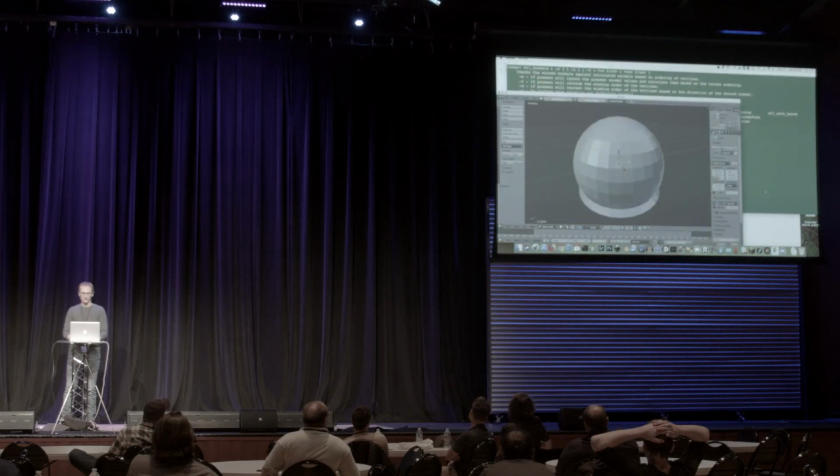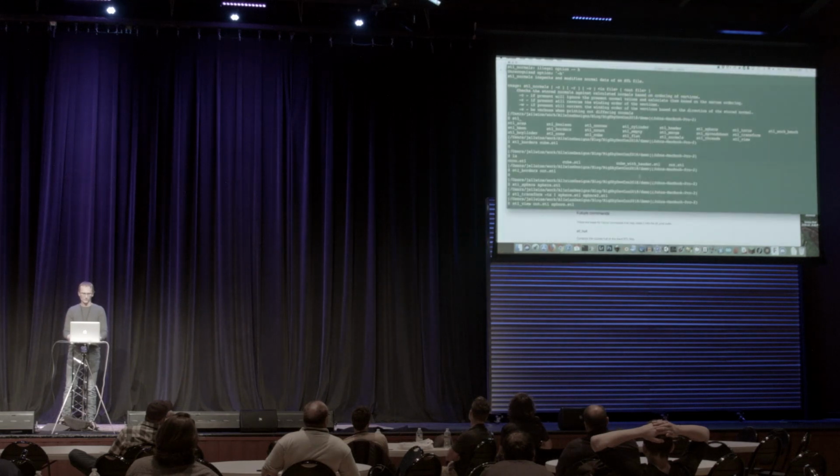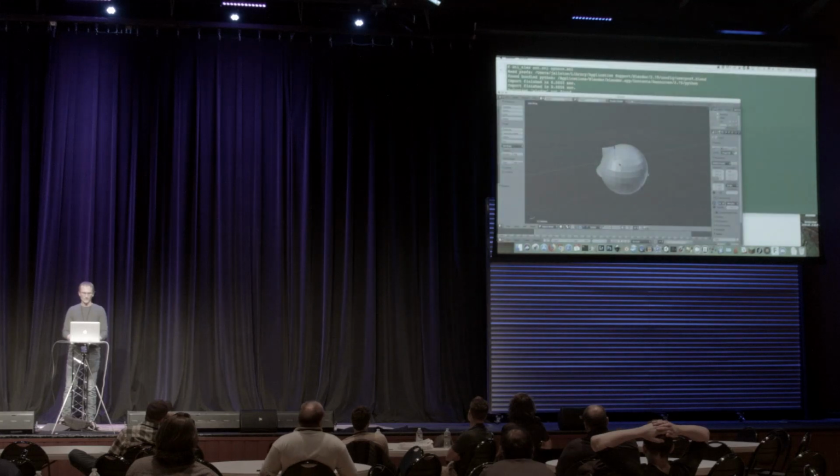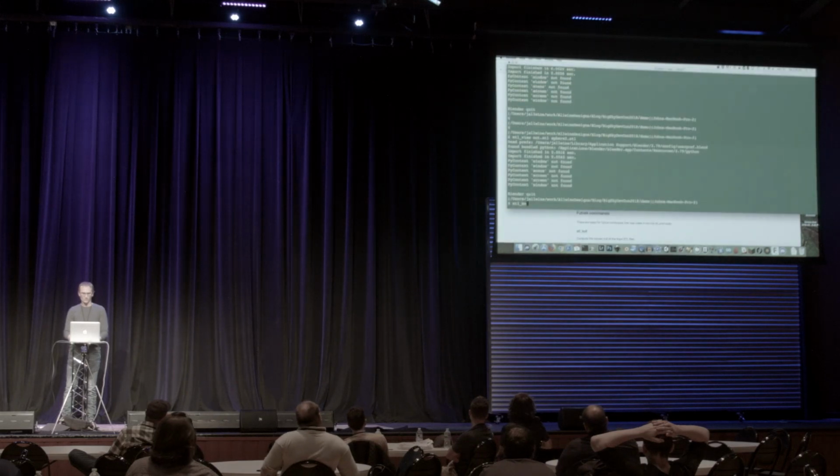Let's just look. Oh, I meant sphere2. Okay, so now I'm going to subtract this sphere out of it. STL boolean A out.stl B sphere.stl dash D will do the difference into out2.stl.